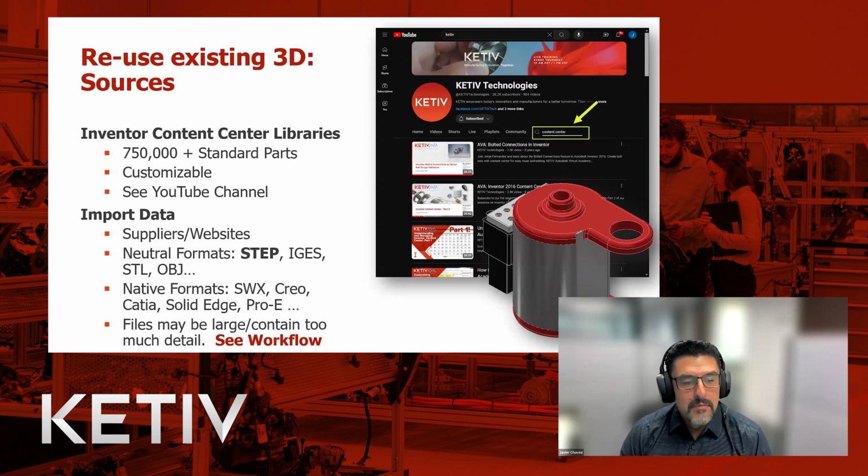If you're going to get data from vendors or suppliers, you're going to have to import that data from somewhere. If you're fortunate enough that they have the same tool, they could just bring it in, right? But in a lot of cases, you're going to have to work with neutral formats, right? Exchange formats like STEP or IGES, or you can see some of the lists there. STEP is preferable. It's probably one of the more common ones.